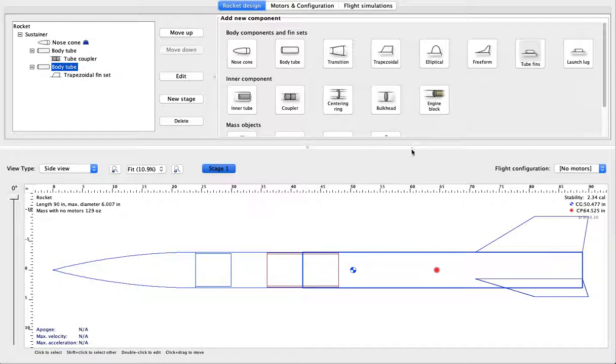Well, a rocket's not a rocket without a motor. So let's go ahead and get to that. Now, there's two ways you can do it. You can make this entire tube your motor. For very big rockets, that's what they do. I know for a fact that USC has a minimum diameter 8-inch rocket, and it's all full of propellant. When I say minimum diameter, I mean this entire thing is full of propellant. But for most rockets, that's not the case.